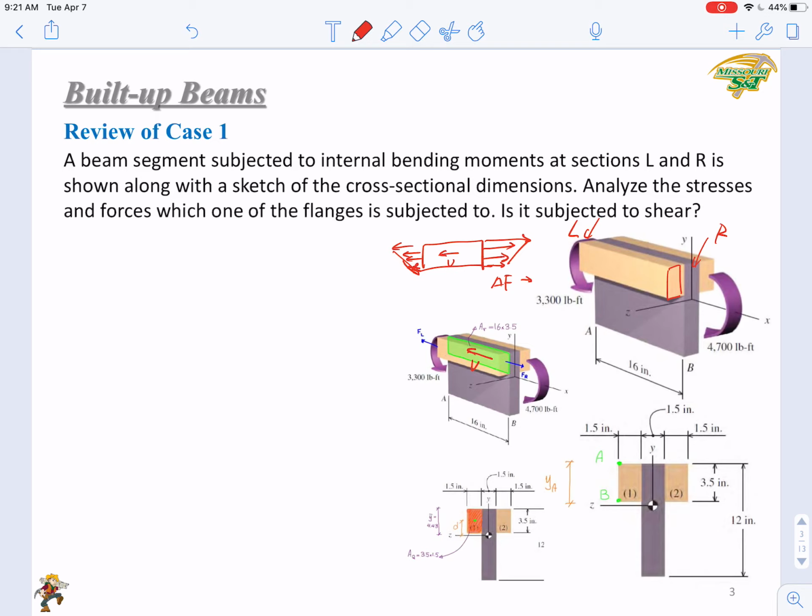So how did we derive the shear equation? Do you remember that? The delta F can actually be calculated as the right pointing stress, sigma R minus sigma L, times A. This is the delta F. We can extend it into delta M y over I times dA, and we also combine the y dA into a Q. Then this equation can be rewritten as delta M Q over I. So here we calculated the delta F.